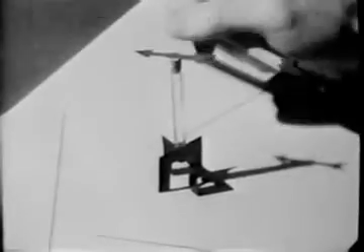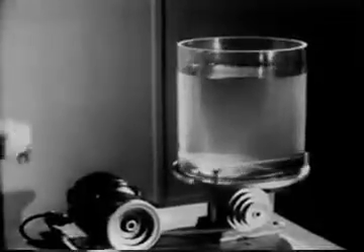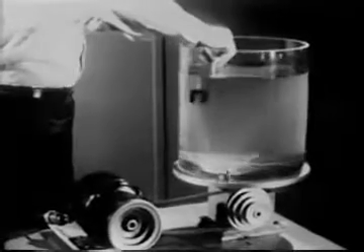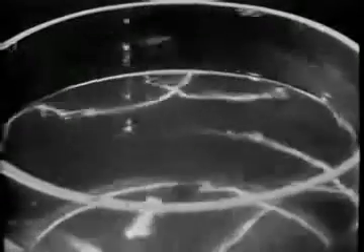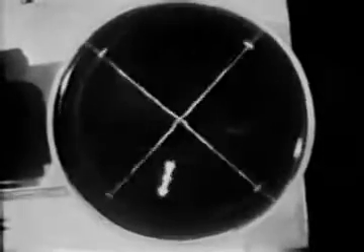This gadget is a vorticity meter, which floats in water with its axis vertical. The two vanes at the bottom are driven by the angular velocities of two mutually perpendicular fluid lines, so the arrow at the top turns at a rate equal to the average of these two. That is, with half the vertical component of vorticity of the lump of water in which the vanes are immersed. This tank has been on the turntable for a long time, and viscosity has forced the water into a rigid body rotation. The vorticity float rotates almost exactly with the speed of the crossed white lines on the bottom of the tank.